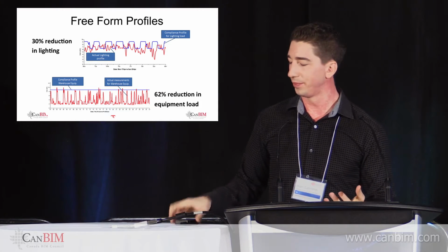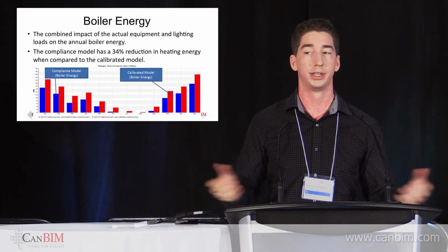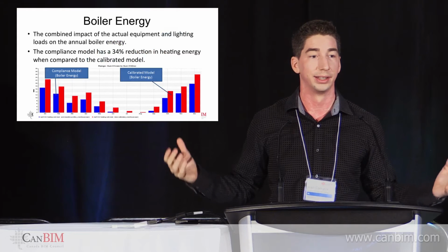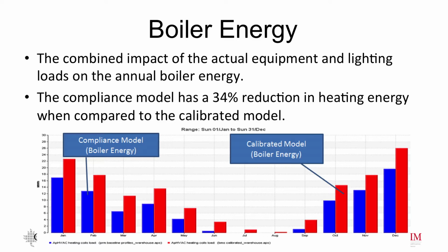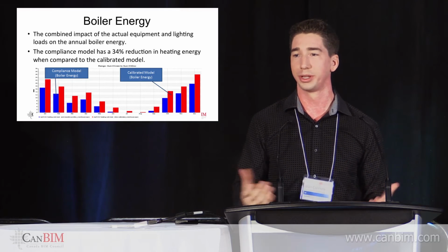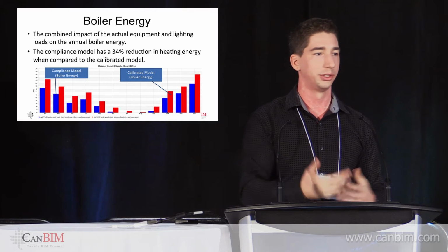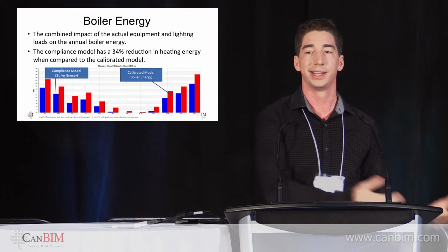So what does that mean? It means we have a lot less heating energy being generated in your building. So when you have a lot less heat, what's going to happen to your boilers? The boilers are saying, okay, it's not as hot, we don't have as much free heat, so I need to generate more boiler energy. And your cooling load, your chiller is now oversized. You have more chiller capacity than you need because you have less heat.